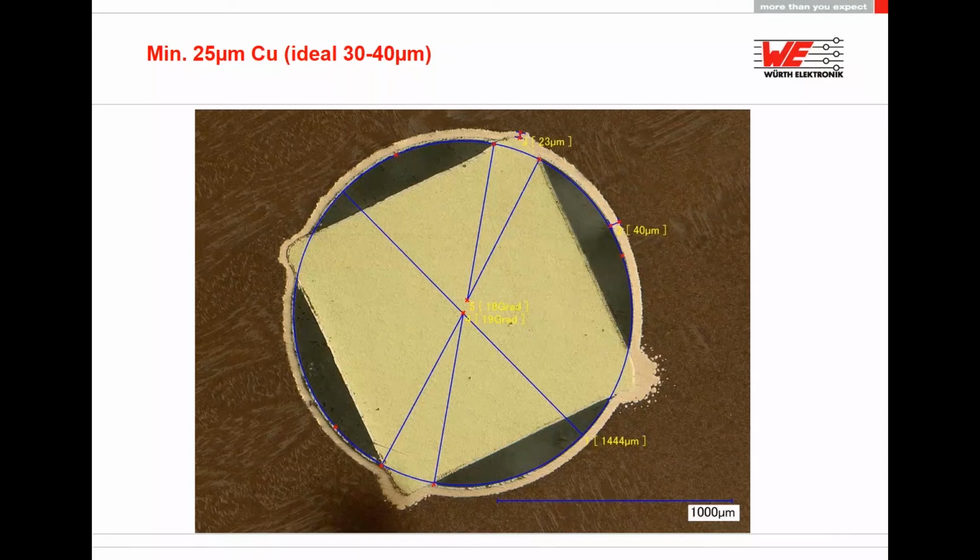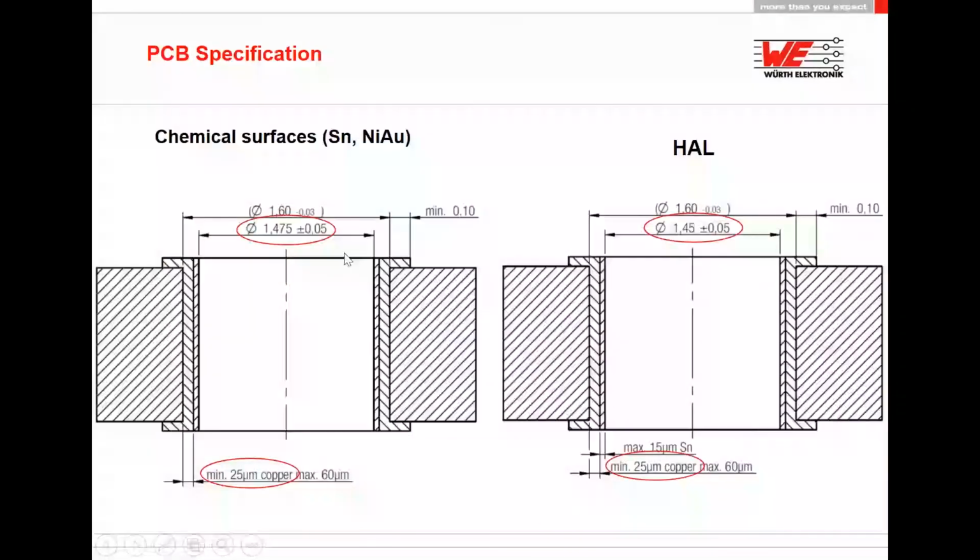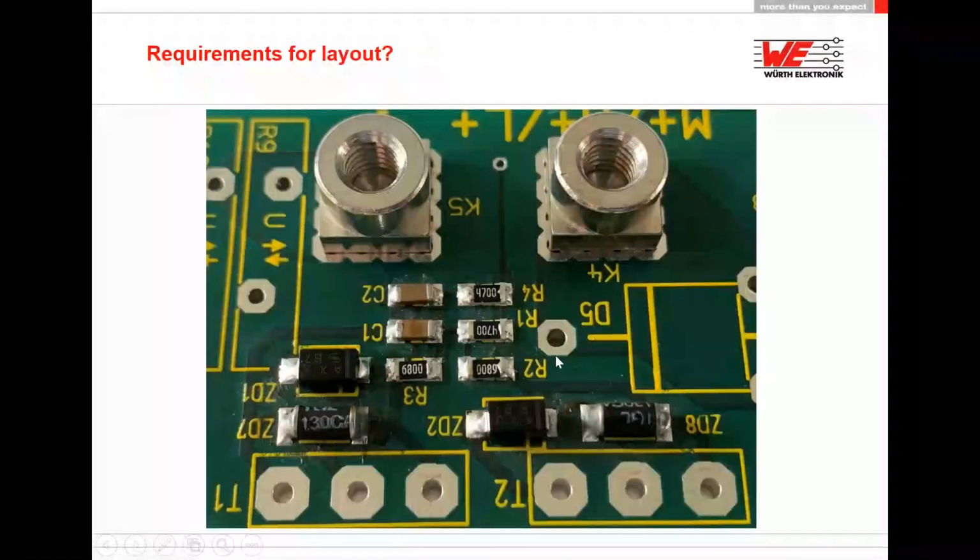What you need for the drill size for the copper bar is the same specification as we use here. It doesn't matter which one you choose. You can use this one or this one. It's not critical with copper because we can't damage any FR4 material. So even if you use a smaller size like this, you just have more deformation in the copper, and that's it. So it's not a problem to use it with copper bars or brass bars.